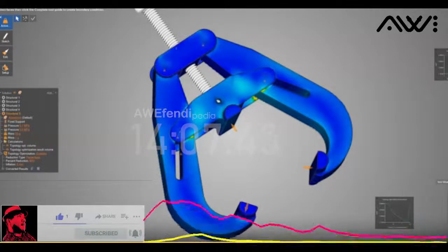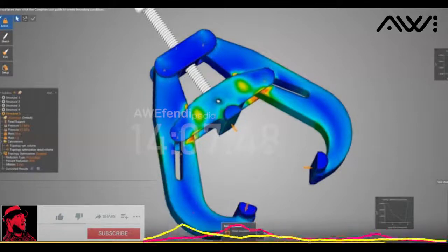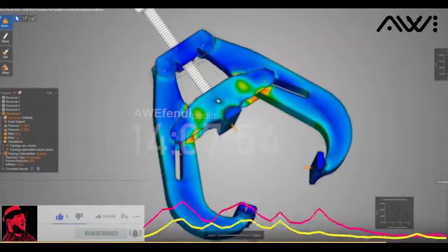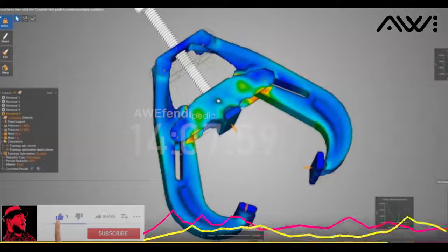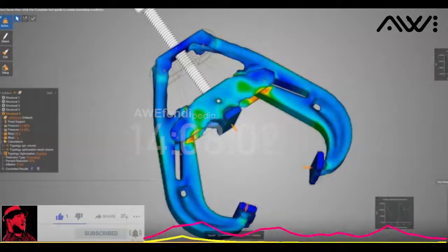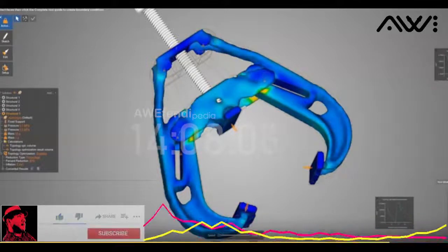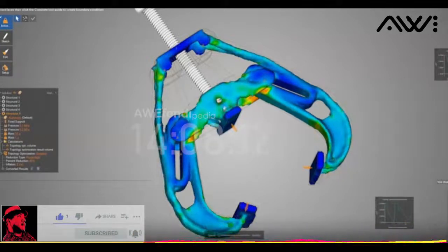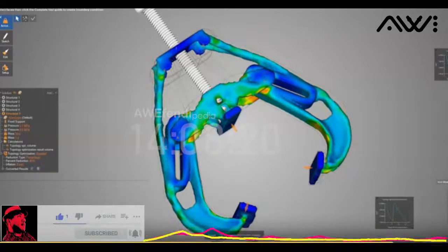Now I'm gonna come back in, let's move the speed down because I want this sucker just to fly through and give me some quick results here. So here we are, quickly iterating. And you notice just with that small little change, how quickly my result is happening. So think about if you move that slider all the way up to get more accuracy, you're gonna get a lot more detail here on everything. And then of course we can take this, save it as an STL file, convert it over to a CAD model, BREP surface, and then go drop another cut in it or give it to somebody else to do some work with it. So this is a great phase and we're iterating through this entire process just to see what's going on.